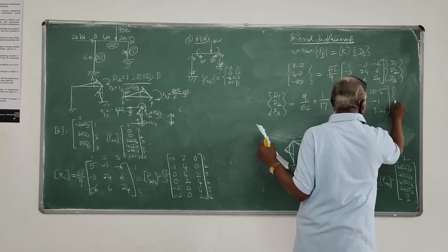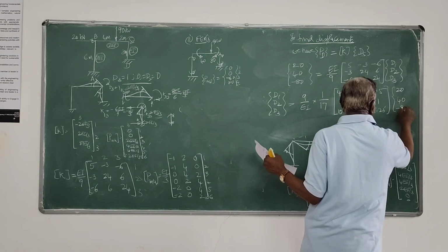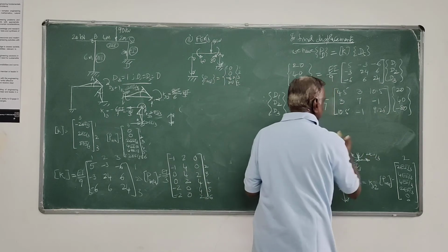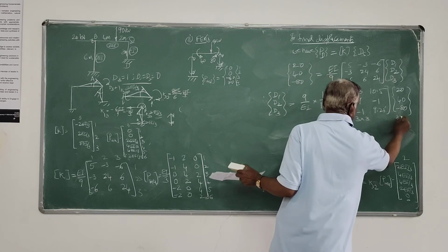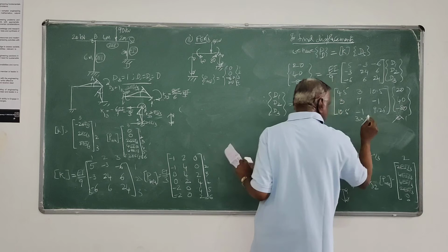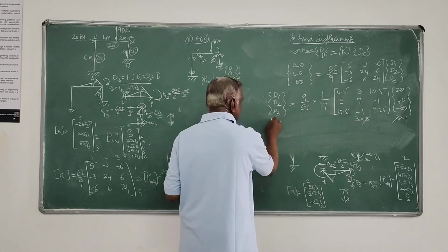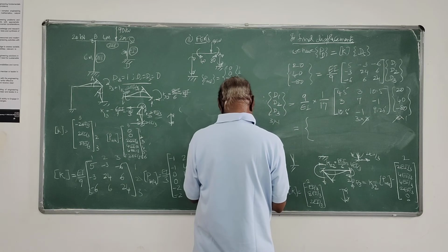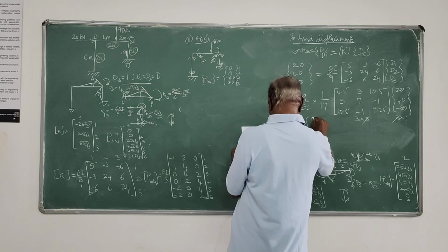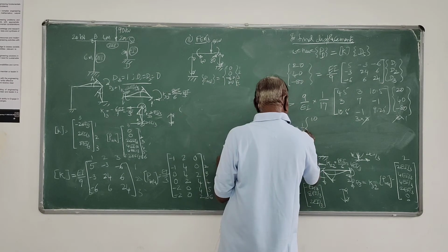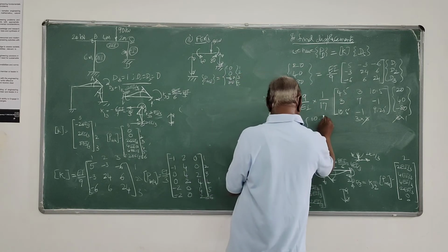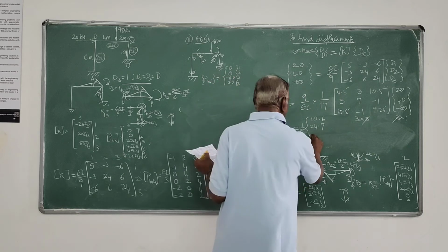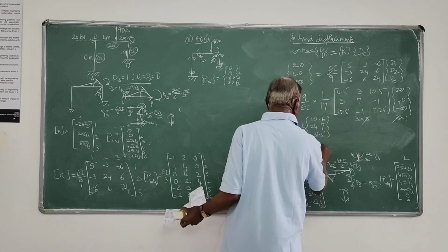So this is multiplied by PD, that is 20, 40, minus 80. This is another exercise you have to do. If you just multiply this matrix and this matrix, we can multiply because this is 3 by 3, this is 3 by 1, the column count is equal to the row count. So the resulting matrix will be 3 by 1. That is exactly the displacement corresponding to that. If you multiply, you will get the displacement directly. I have the result here. It is 1 over EI into 10.6. Then I have 24.7. Then I have minus 33.5. These are the displacement values.